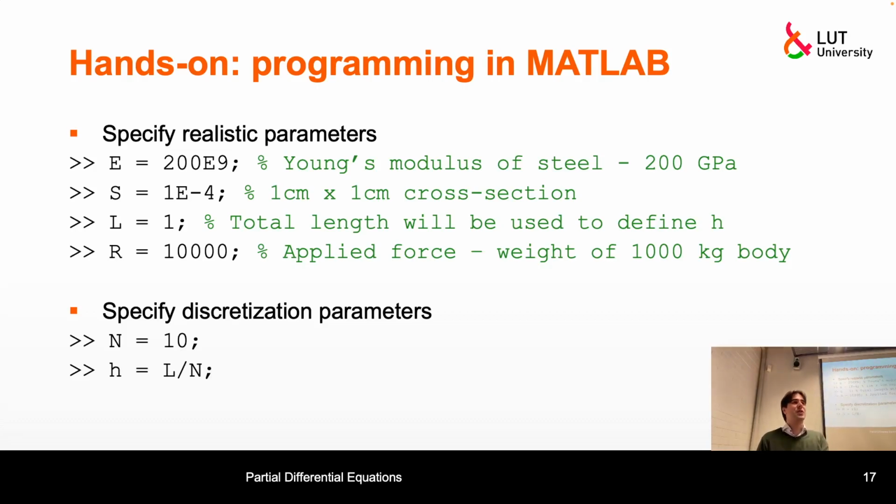It has to do with your intuition, because using some simple test problems, you help develop this intuition that I already mentioned, that allows you to predict solutions, at least qualitatively, how they must look, in certain cases even quantitatively. And if you are using some random values, say you put just 1 for Young modulus, and you put 1 billion for the force, you have no idea how it's related, what kind of displacement you would expect.